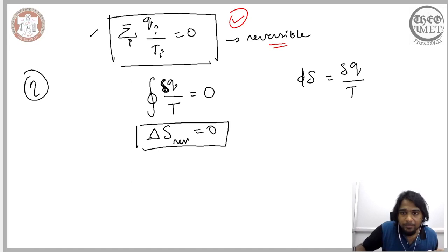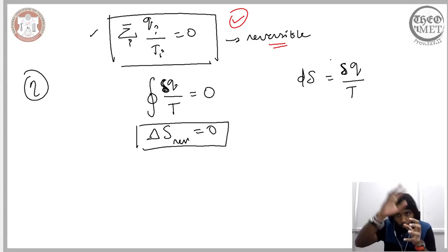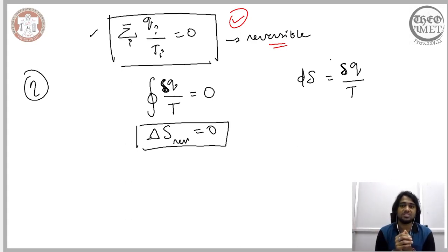So we see that these parameters relate to a thermodynamic variable that we are familiar with, and that thermodynamic variable is nothing but the entropy. What we observe is that even though the change in the entropy relates to the degree of irreversibility for each step, and there is some amount of irreversibility involved, since we are considering the overall reversible process, the overall change in the entropy is equal to 0 for a reversible cycle.